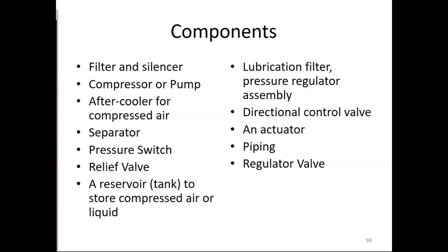And same thing goes for pneumatics. If you end up blowing out your seals in pneumatics, you're going to have that same kind of issue. You're going to have to crawl through everything to make sure which seals are good, which seals are bad, what's cracked, what's broken, what's not. It's just not worth it. You have relief valves for that reason.